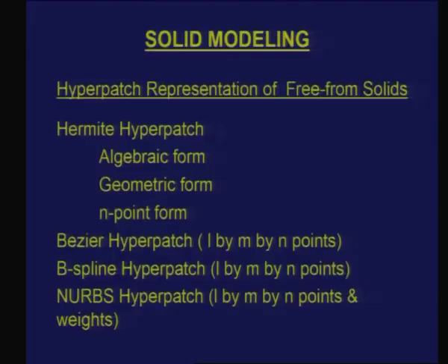Now, one of the logical extensions of modeling solids is basically an extension of the parametric curves and surfaces, which we discussed, to solids also. Just like we had a Hermite curve and Hermite patch, I may have a Hermite hyperpatch, which is nothing but a piece of solid which is bounded by 6 surfaces, and you can have 3 different forms, just like we had for curves and surfaces.